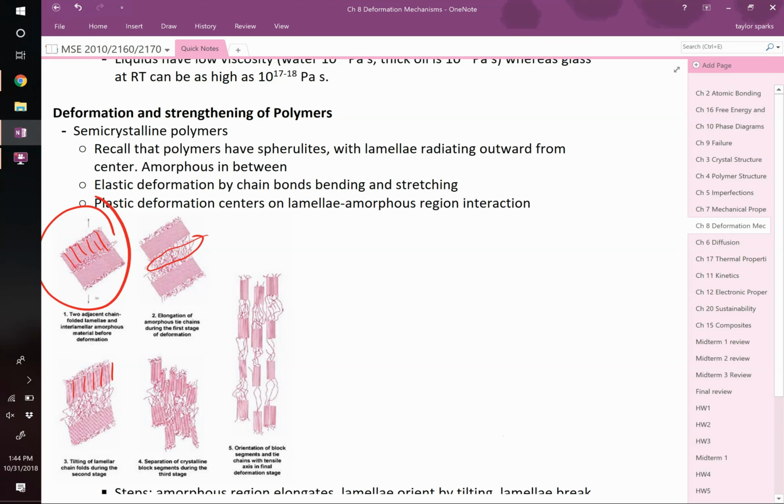And the way that they deform polymers in one direction is by drawing. We showed this with the nylon 6/6 video. Remember the nylon 6/6? They grabbed that interface, they pulled it up, and they were winding it around the rod. As they were doing that, all the polymers were sort of starting to line up. And if you do that over and over and you keep on drawing it, or you draw it down to smaller and smaller diameter, you can really make high-strength polymer fibers.